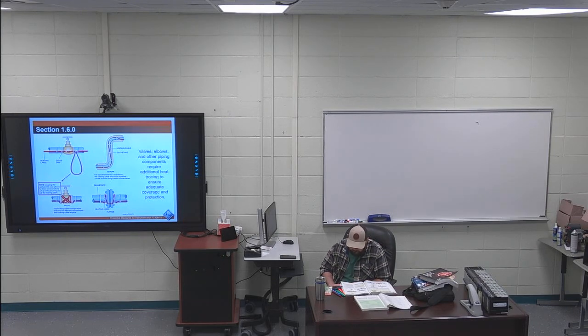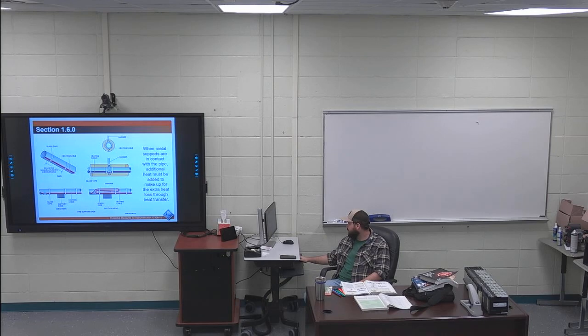First bullet point on page 15, first sentence is highlighted. Heat tracing cold leads. The section of the power wiring leading to the pipe surface must be positioned to penetrate the insulation in the lower 180 degree segment of the pipe. All that's saying is, if you look at the picture, this heat tracing comes in from the bottom, and that's because, like we've said, all the pipes still have insulation on them, and if we enter from the top, that creates a leak point.